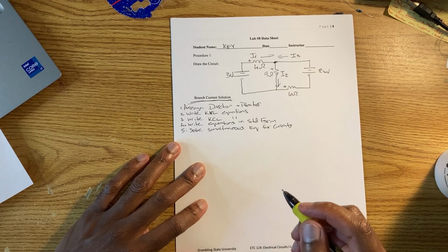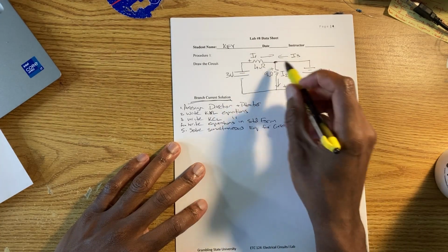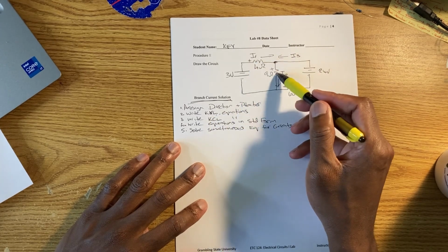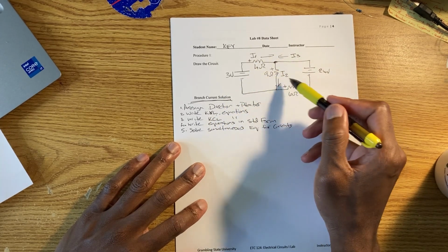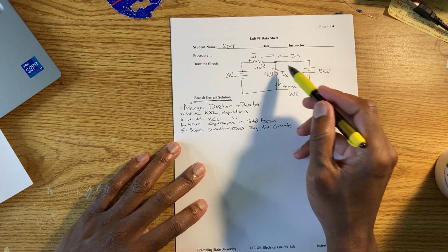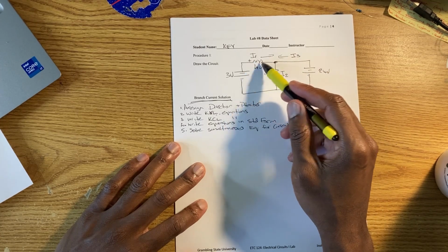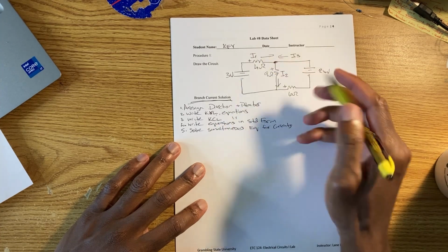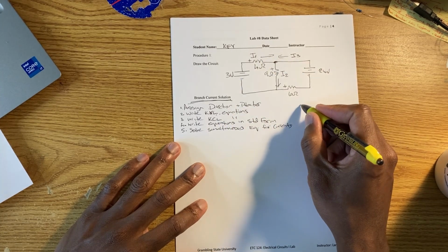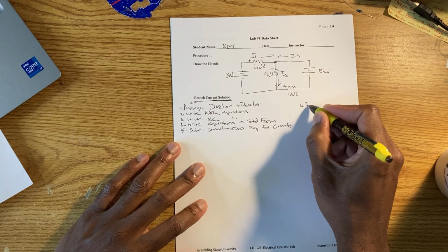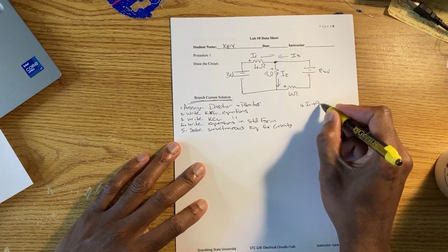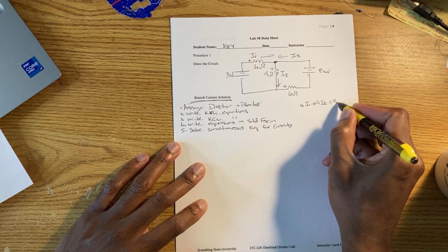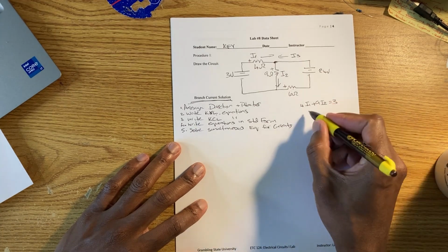So the equations are going to be, we can start right here. Again, what we are writing for the KVL, we are just saying that the voltage drops are going to equal the source. So the voltage drops here will be equal to the source. And so to find the voltage drop, we take the current going through the resistor times the resistance of the resistor. So I can start right here. I can say that 4I1 plus 9I2 is equal to 3. That's essentially what we are saying.